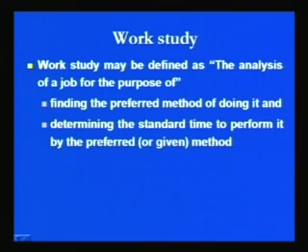Work study is defined as the analysis of the job for the purpose of finding out the preferred method of doing it and determining the standard time to perform the job by a given method. The work study basically involves two aspects. One is analysis of the existing method of doing the job, so that the best method for carrying out the job can be developed after analyzing the existing method, and it uses the method study for study of the existing method and developing the new method, which is more effective and makes less use of the resources.